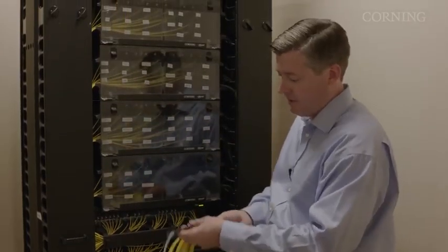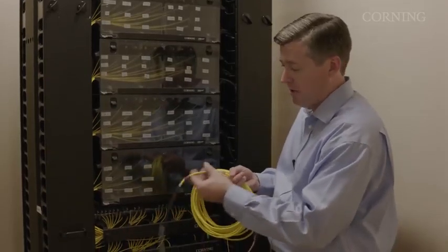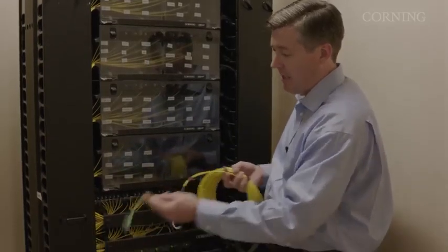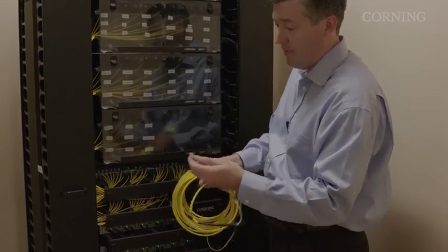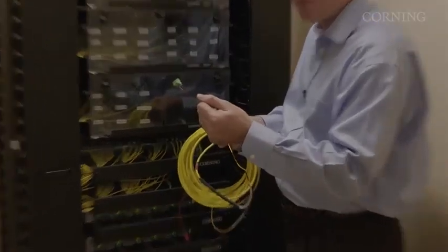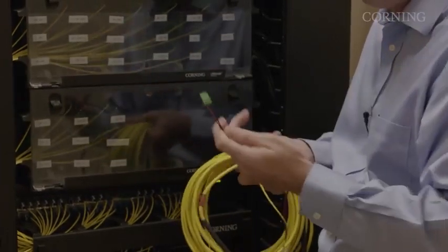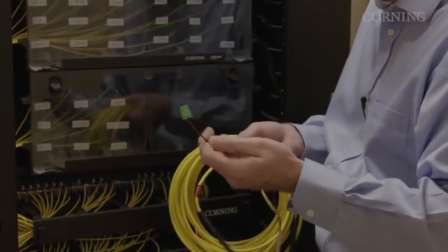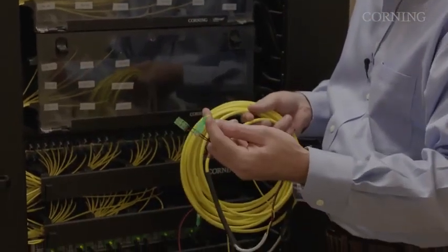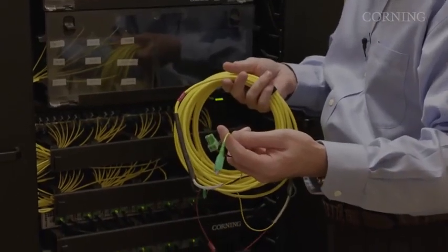What that composite cable looks like, so this is an example of the composite cable that's going to the rooms. So you'll see I've got a composite cable, I have a copper pair, which is my power, right? So this is where I'm patching into my patch panel from the IDF, and this is also where I'm patching into the ONT in the room. And I also have my fiber connectivity, all under the same sheath.